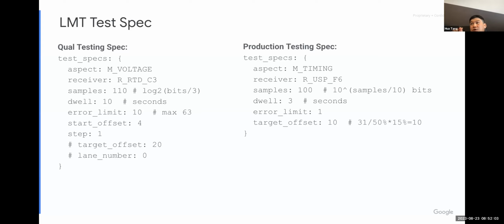That's your assumed correct data. We want to see how good the signal quality is, so we move the sampling away from that calibrated, trained center and sample the data at the same time, and compare with the data you sample at the trained data center. Okay, got it. So you compare whether it's the same or different. If it's different, that's an error.